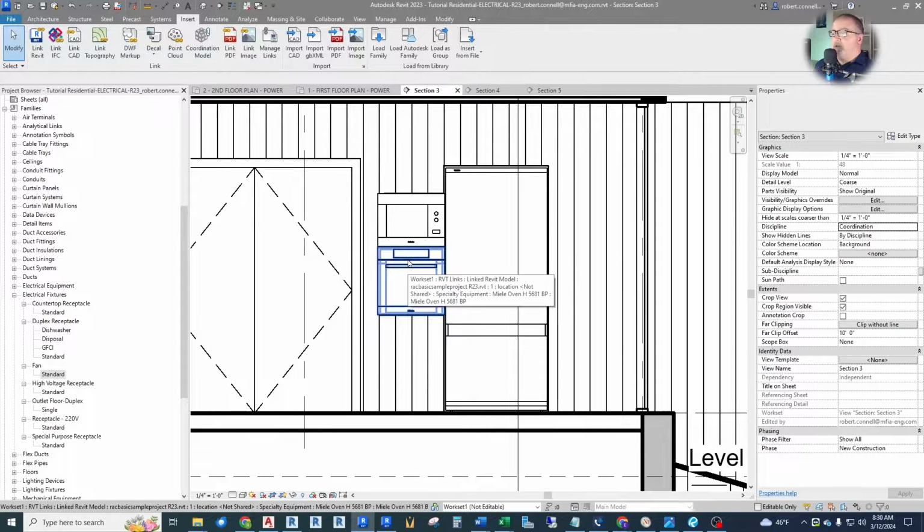Okay, so refrigerator, again, you start looking at specs on these things. They typically can be around 800 to 1,000 watts, depending on how big it is, maybe 1,200 watts. We're going to go with 800 for now. The oven, I'm going to figure at a full range power of a full 50 amp, 240 volt outlet for that guy. So that'd be more like an 8, 9 kW. And then this microwave, they're typically down around 1,200, 1,250, up to 1,500.